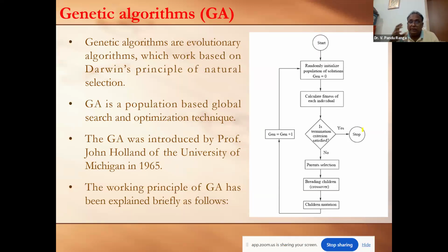So that's why fuzzy logic is called a knowledge-driven system, consisting of a knowledge base, which once again consists of database and rule base. The success of the fuzzy logic controller always depends on how effectively we design the database and rule base of the fuzzy logic controller. Therefore, the designer of the fuzzy logic controller should have an idea of the domain knowledge. Whereas in the case of neural network, the designer need not know anything about the physics of the system.